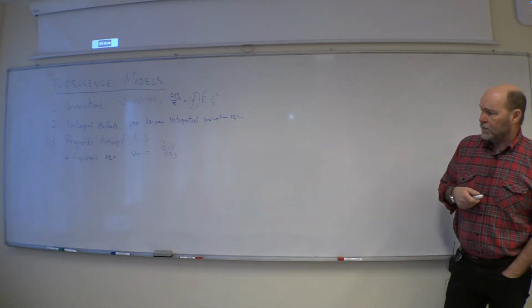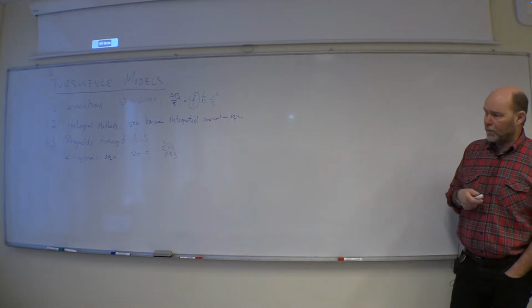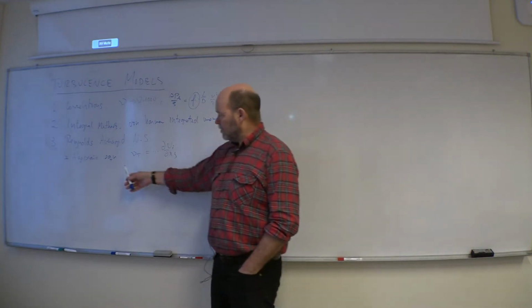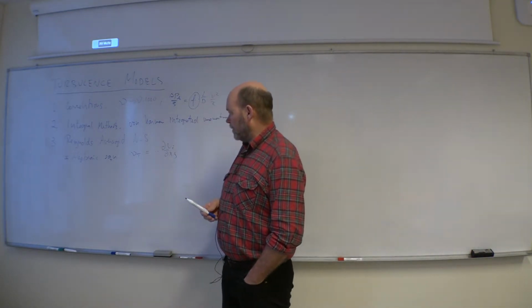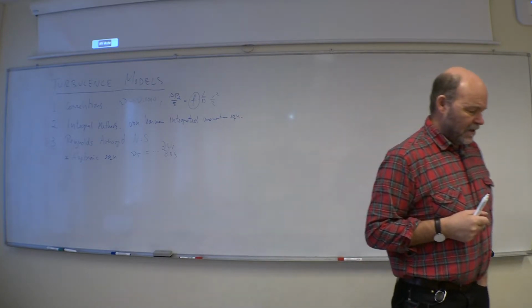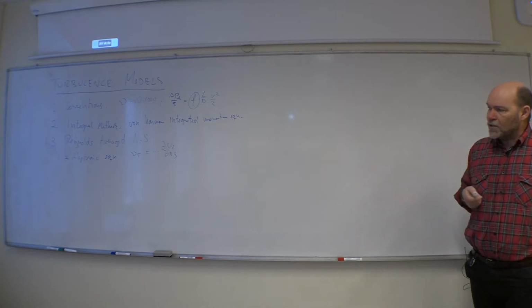And quite a big family of these, Baldwin-Lomax, Smith, a whole bunch of them. But it's only an algebraic equation. So that means if you have a turbulence in one spot, then you have to deal with it there. It doesn't move around. There's no transport equation.